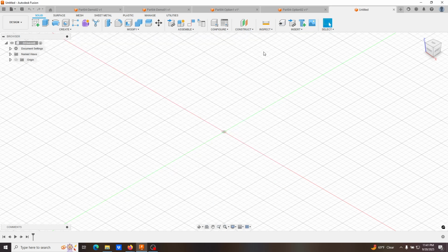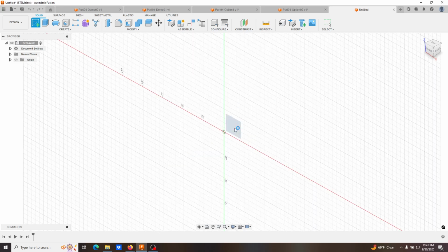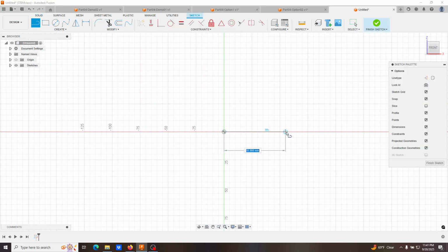There we go. All right, so I'm going to go Control Sketch, start a line. I'm going to go here. Now you'll see how it does the horizontal and vertical. So since I don't want to do perpendiculars this time, I'm just going to hold control while I put these here, and I'll just lock to here, and then I'll press escape. Then what I'll do is I'll just go back and put my horizontal and vertical. Also, I could have just drawn a good old-fashioned rectangle, but actually, you know what I'm going to do? I'll leave it like this.